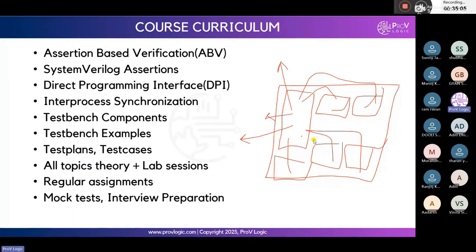But in C language, it is easy to debug any assembly language program or even a normal high level language. That's why for the processor we use C language, and for the remaining entire chip, we use UVM. Okay, clear everyone? That's why in SoC verification we write C test cases.